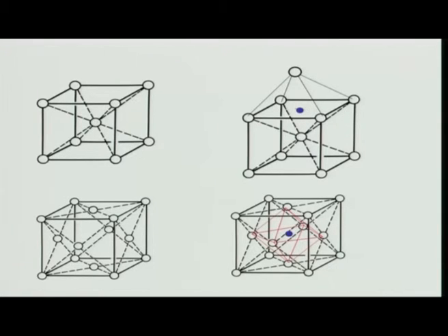Why is it called an octahedral void? Because if I join these atoms, I form an octahedron. An octahedron has 8 faces. You can see here 8 faces, 1, 2, 3, 4, and the bottom one also, so 4 plus 4, 8 faces: top 4, bottom 4. At the center of that there is a void, and in fact for BCC iron the void sits on this plane. So there are many such octahedral voids. Similarly, there are tetrahedral voids.